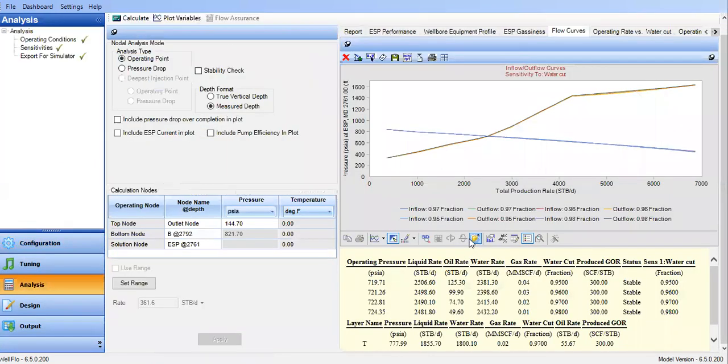But as far as modeling commingled production is concerned, we have done that. And this is what we have. You add a new reservoir, you need to construct the IPR of the existing reservoir and the new reservoir, and you get the IPR of the commingled reservoir. Then you bring them into nodal analysis and do sensitivity analysis, for example, for the water cut. Okay, so I think that's all.